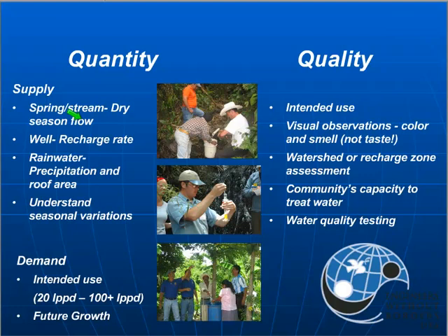What is the recharge rate of the aquifer? If your demand is 50 gallons per minute, and when you pump at 50 gallons per minute, the aquifer draws down significantly, the water levels are decreasing and the well dries up. You need to understand what the capacity of that is compared to that demand. So you need to do some sort of recharge test, or get at least some anecdotal information from other wells, talking to other people with wells in the region or local drillers.